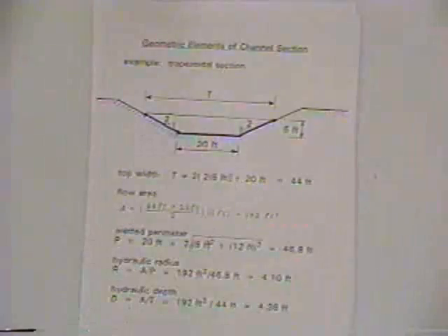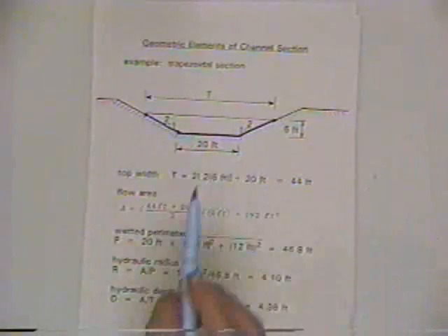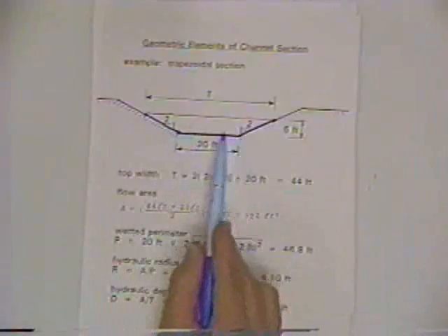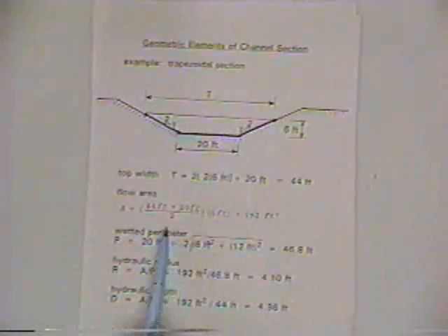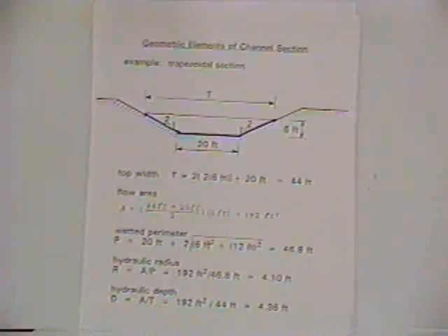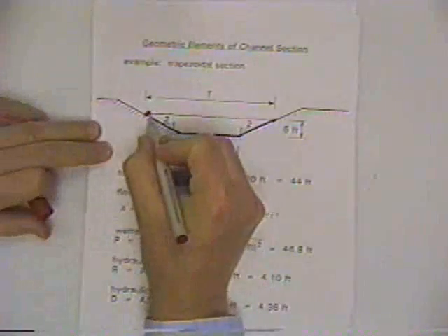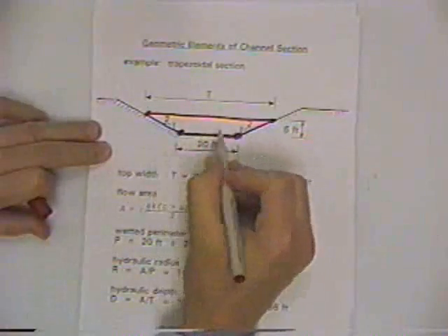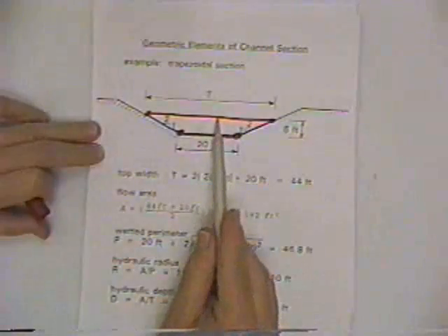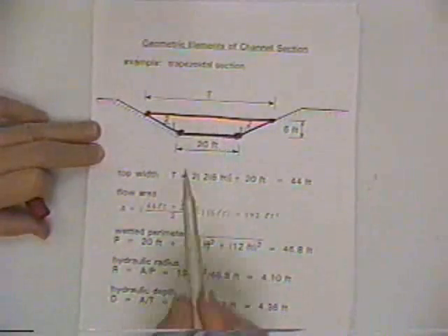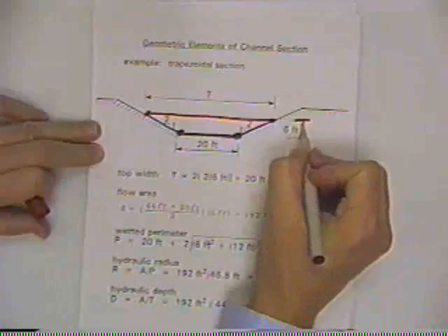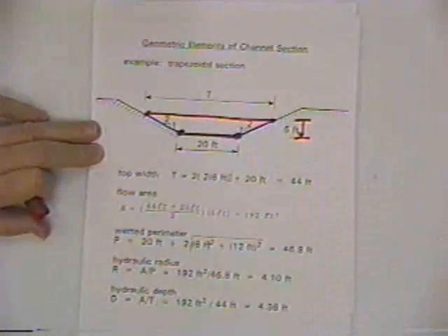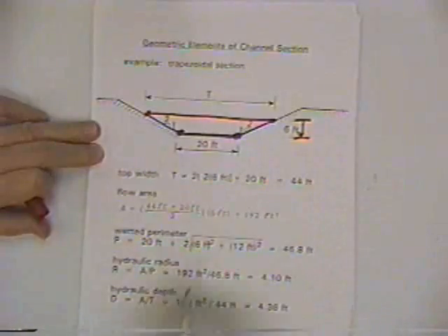And so that's the wetted perimeter, and the flow area here to plug into Manning's equation just from geometry would be the top width plus the bottom width divided by 2 times the depth. So we're really out of fluid mechanics into geometry, but geometry is a big part of solving fluid mechanics problems. And so just taking the top width plus bottom width, dividing that by 2, and multiplying by the depth, that would give you a cross-sectional area of flow.